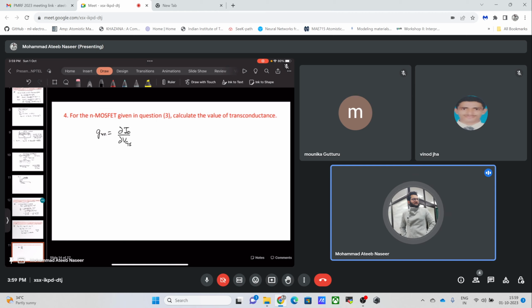Considering the parabolic approximation of the bands, the effective mass along one transport direction and another can be different, and the density of states is hugely dependent on the effective mass of the material. So this Gm also depends upon the effective mass of the material.